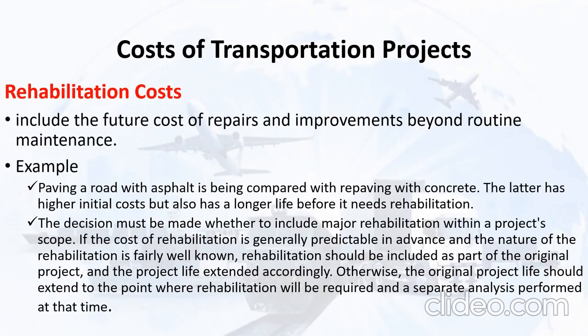For example, paving a road with asphalt or tar is being compared with paving with concrete. The latter has a higher initial cost but also has a longer life before it needs rehabilitation. The decision must be made whether to include major rehabilitation within a project scope.